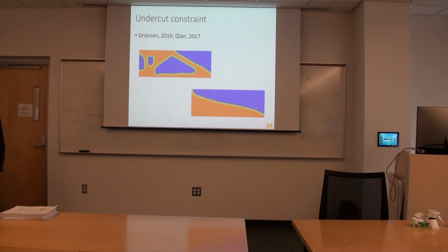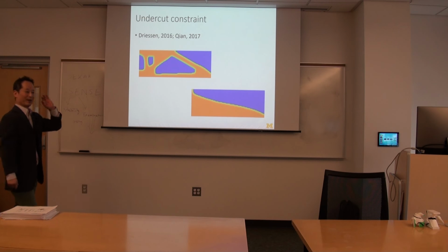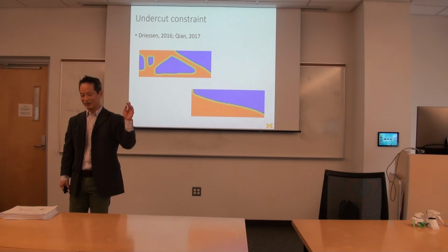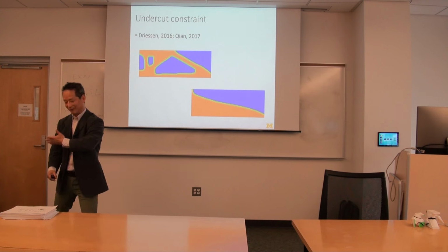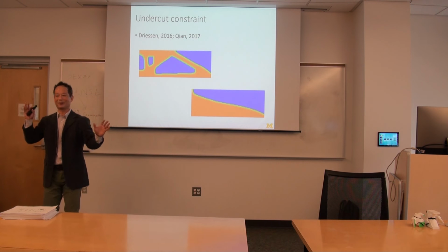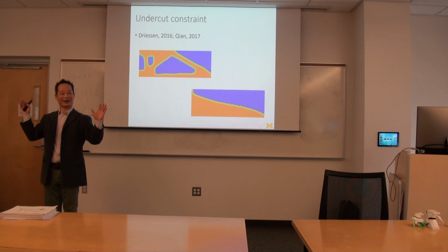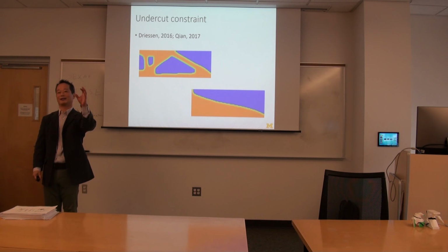But if you look at this, really, after applying the undercut constraint in this direction, why use topology optimization in the first place if that's the result you want to get, right? So that was really the question mark posed by this work. However, if we look at this from the new viewpoint where I am designing multiple pieces, all of a sudden each of the parts can be undercut free, but still as a combination, you can create holes within it to optimize overall structural performance.